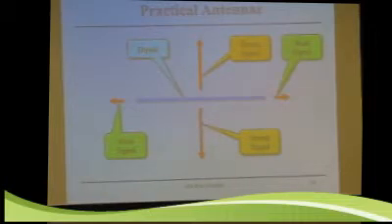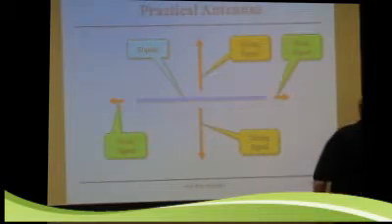What some people do, if they have one really good tall site, say they've got one tree that's better than all the rest, is they'll put the center of the dipole at the tree, and then the legs will slope down, and you might even tie it off to a fence. What you would need to do is make sure you have an insulator there. Essentially, you don't want anybody to be able to touch the wire because they could get RF burns from it. But if you had it far enough away that this rope would be maybe 8 or 9 feet up, then it would be pretty safe to do that. And this is what's called an inverted V.